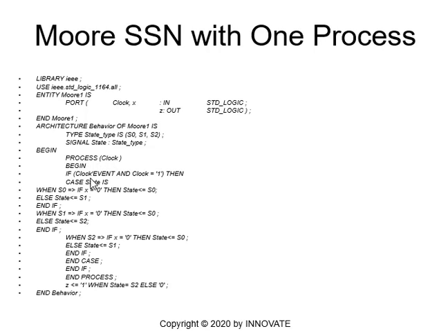Begin. If clock event, case state, when S0, if X is 0, then I will assign S0 to the variable state, else I will assign S1 to the variable state. When S1, if X is 0, I will assign S0 to the state, else I will assign S2 to the state, end if. When S2, if X is 0, then I will assign S0 to the state, else S1 will be assigned to the state, end if, end case, end if, end the process.